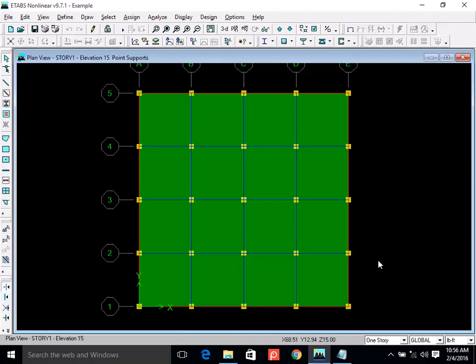ASCE requires around 50 or 60, maybe 50, I'm not sure, I'll have to check. So ASCE loads are on the higher side. I strongly recommend that you don't just remember these numbers, you also have a physical idea of what 30 pounds or 40 pounds or 100 pounds per square foot means. Everybody is clear about this concept?